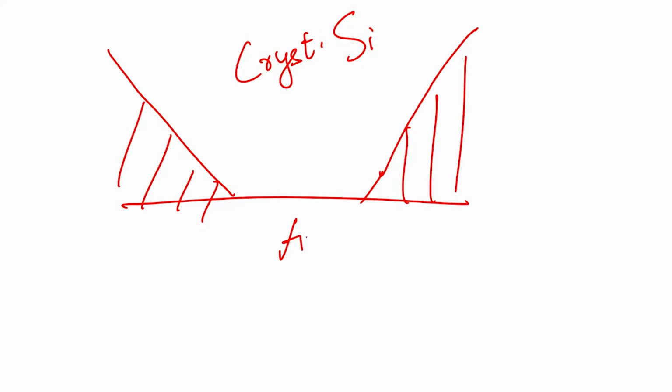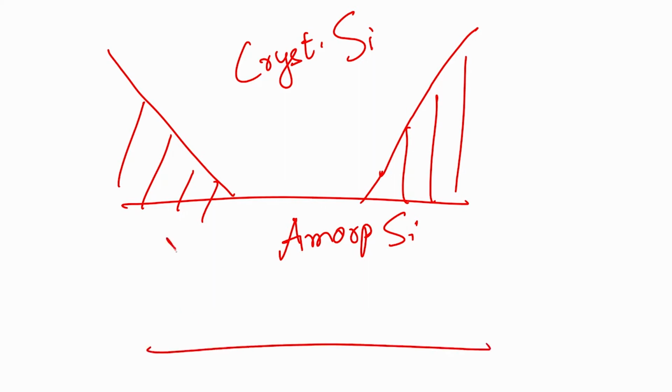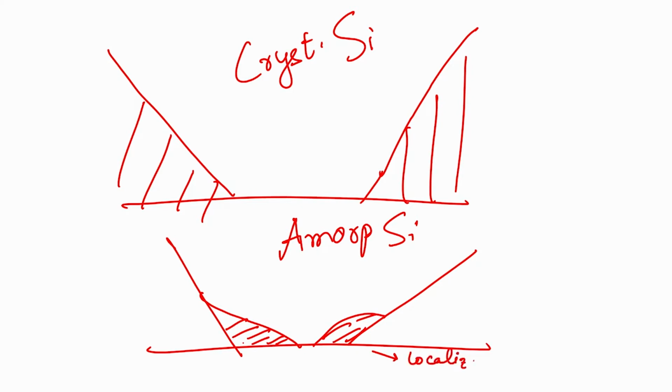Whereas in case of amorphous silicon, there are some tailing states which also form the part of density of states configuration and have some allowed states, and they are called localized states, in the sense that their spread, which is in quantum mechanical terms called wave function, is very localized, which means they are not continuous states, or in simpler terms you can think of them like puddles.